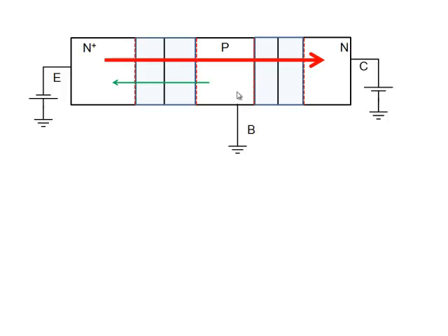So that's the picture that you have here. Is it acting like a transistor? Do I see a transistor here? How do I test whether it's a transistor? What do I need? I want my collector current to be independent of collector-base voltage, right? That's the output voltage, collector-base voltage. Base is ground, so I want my collector current to be independent of, or insensitive to, collector voltage. And I want my collector current to be very sensitive to emitter voltage.